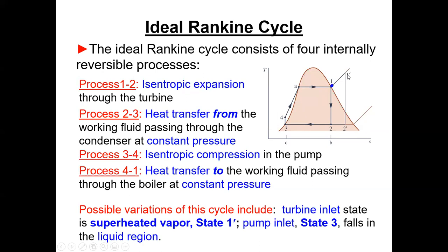Okay, possible variations. We talked about turbine inlet state, superheated vapor, been all over that. And pump inlet state, state 3 falls into the liquid region. Again, this condenser, we're gonna get it over here someplace to make sure that we protect the pump. We go straight up to there.